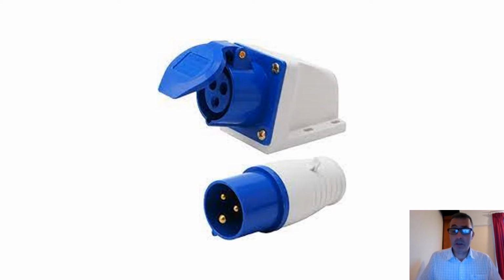This is an industrial socket to provide electrical power to the laser. So the advantage of using one of these things is that you can link that directly to the warning lights. So when the laser is powered up and ready to go, the lights are automatically switched on, and it saves people from having to remember to turn them on during a laser session. Of course, if that's not possible to wire it in that way, the lights can be turned on via a switch on the wall, but that would have to be included in the risk assessment and in the local rules to remind people you absolutely must turn the lights on before you start using the laser.